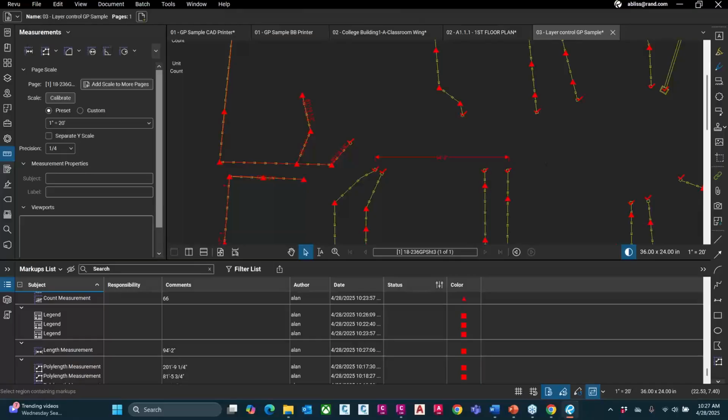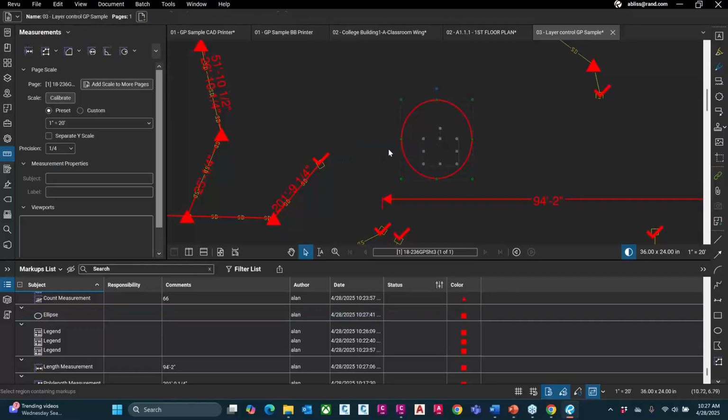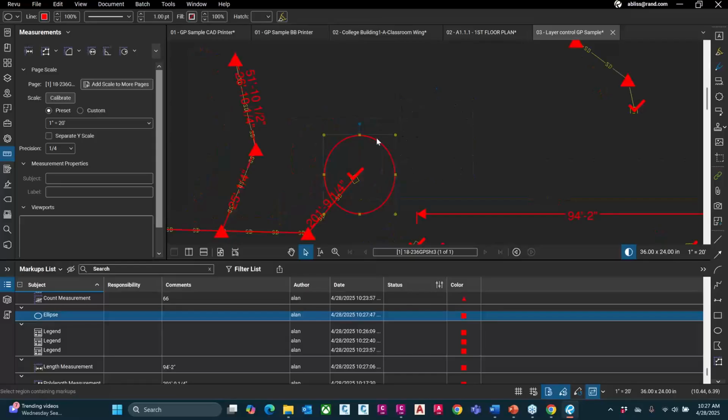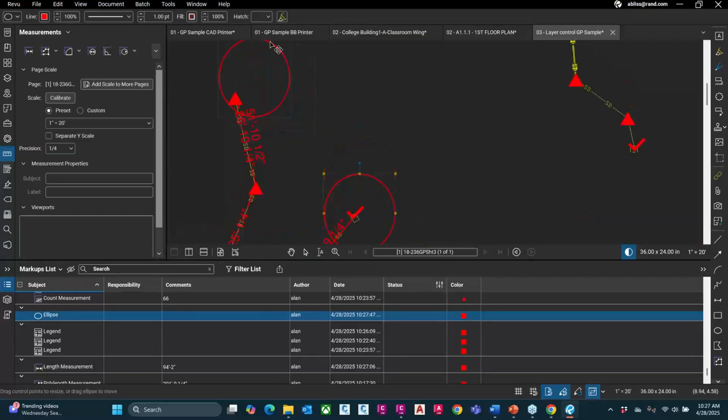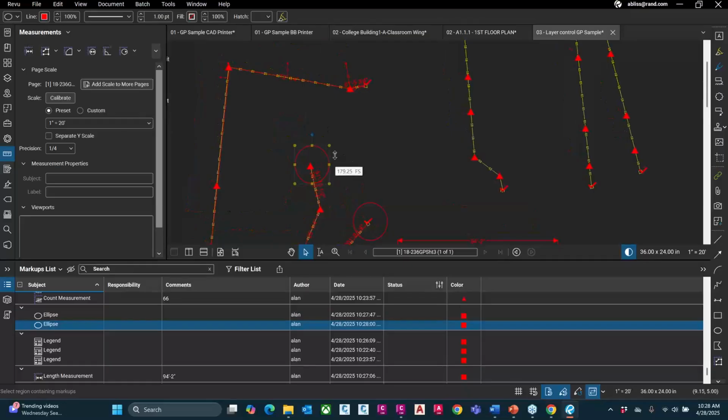Okay, let's look at another couple cool ones. Draw a quick circle. So let's say I've got some type of markup right there, a circle, and let's say that's supposed to be over there. If I hold down Control and then click and hold on that object, and then release, that's a quick copy. Quick copy, and then it gives me that ability to drag and drop.